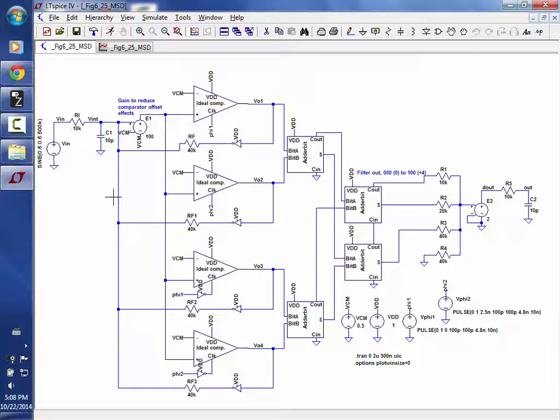Assuming you've got the edges coming in and your data coming out, how would you detect the edges in the data? Remember, in a real SerDes it's not full logic levels. A SerDes is a serial deserializer, so you get a bit stream coming in through a channel like the HDMI that you plug into your TV and connect to your computer. The amplitudes of the digital stream will depend on how far away the TV is from your computer or video player. So the amplitudes change. You're digitizing it, but you want to determine ones and zeros. How would you do that?